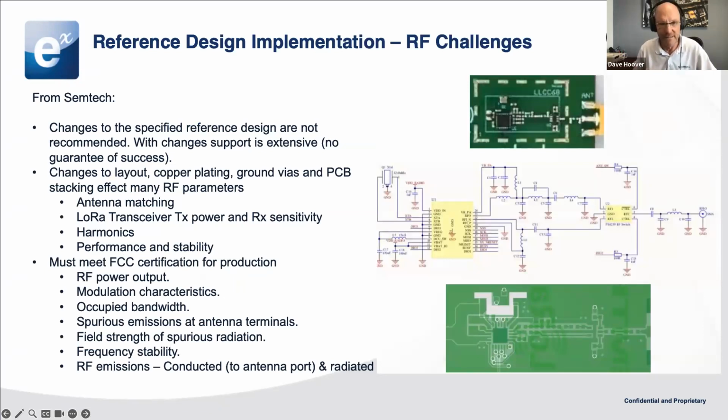So kind of getting into the meat of what we're going to talk about today, what kind of resources are out there? So Semtech has a legacy reference design that's available today. That's basically an Arduino Uno footprint, right? So basically it's a shield that has the 1261, 1262 on that shield.